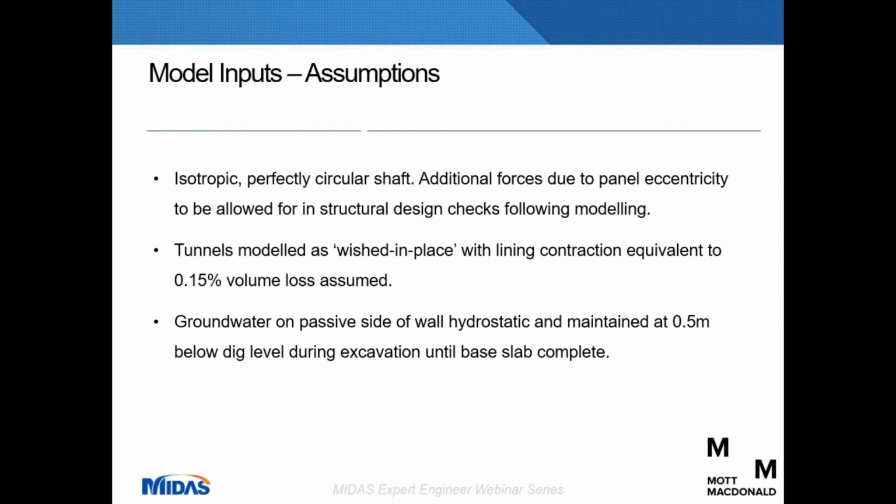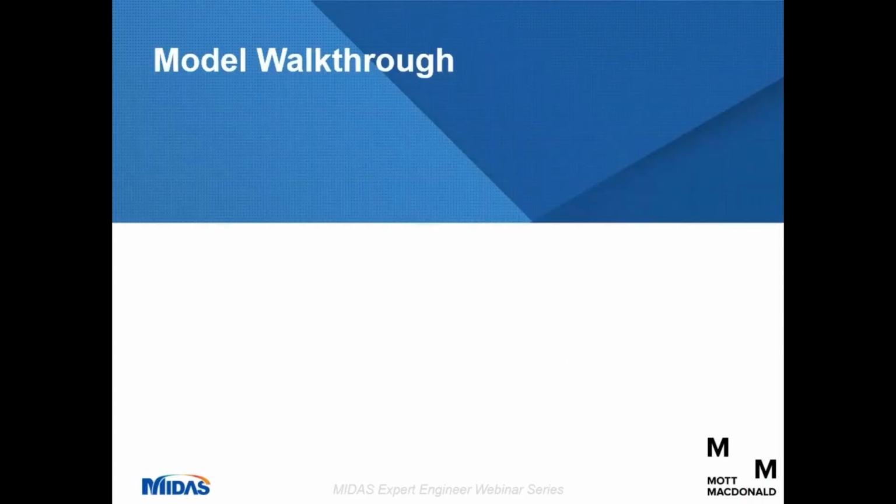And then the final assumption that was made was that the groundwater level within the excavation would be maintained half a metre below the dig level until you cast the base slab, and then the water pressure is allowed to recharge. So those are the key inputs to the model.